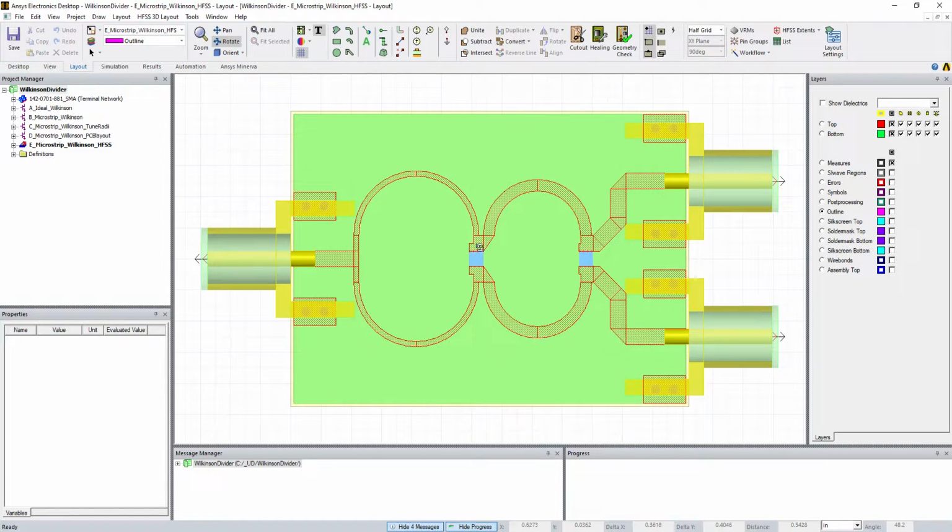And you use a whole bunch of these little bends and things to go from a single input to two outputs that are exactly 0.5 inches apart. The reason I do that is because the connectors line up real nicely. So you're going to want to try to get your connector launches at 0.5 inches, and then the board length will be whatever it is.